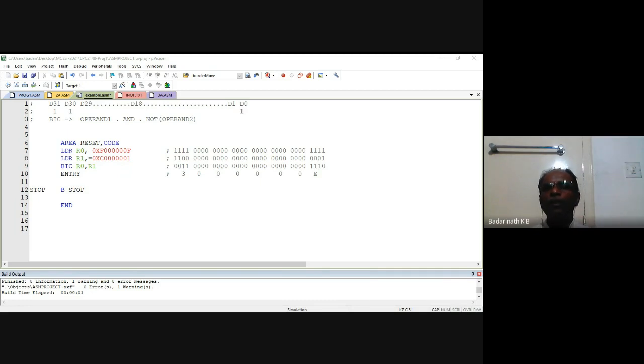So if you don't perform a shift operation, carry is not going to be affected and neither is overflow. The sign and zero flags will get affected, but we generally look at only the zero flag. So whenever we do logical operations, I am interested in testing only whether my answer is 0 or not. Otherwise it's not required. So can you tell me one condition where you perform an operation and check whether the answer is 0 or not? This is one of the beautiful requirements for bit manipulation. What is it that I want to do? For example, I'll come to an example here.